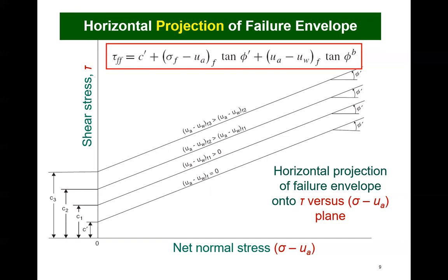This can be done as long as the shear strength surface does not have a warped shape. The purpose of these various plots is to simply assist the geotechnical engineer in realizing that there are limited changes associated with conventional soil mechanics formulations when taking unsaturated soils into consideration.